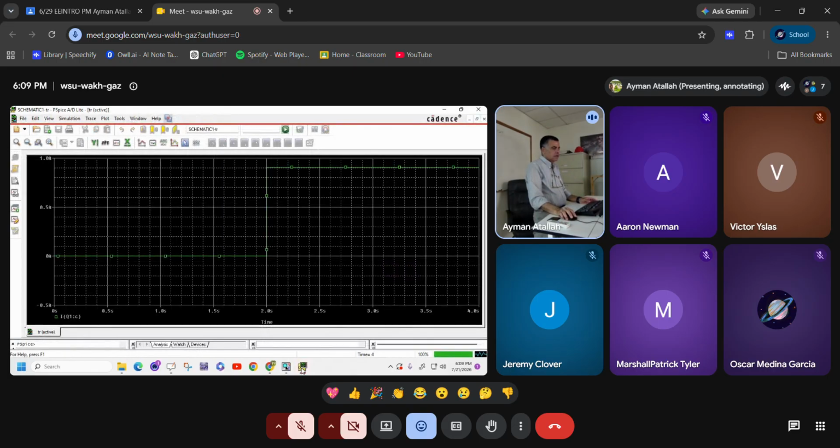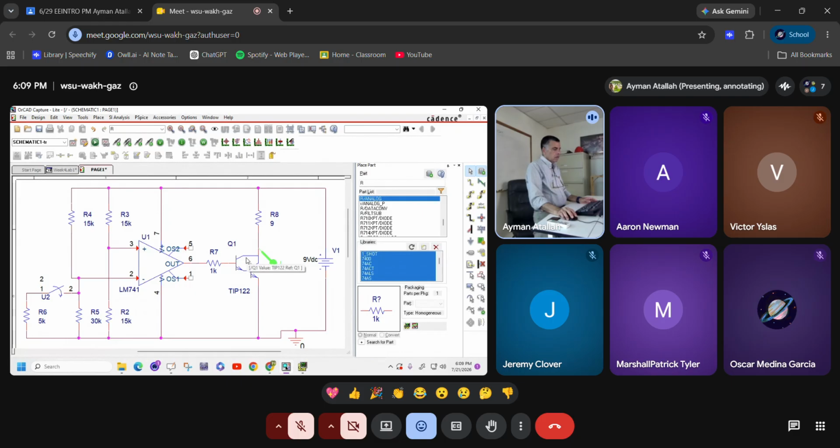So everybody got this. That resistor, you have R8 up there, is that just 9 ohms? 9 ohms, yeah. I make it low to represent the motor. The motor has low resistance. So I just want high current to be delivered to this resistor. So do the current marker again? Yeah, current marker, you can put it here. And this R8 here represents a motor.